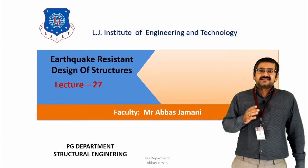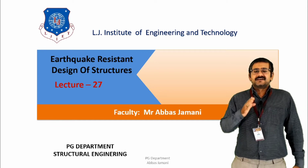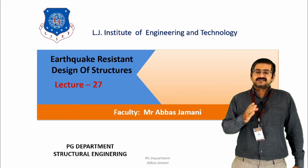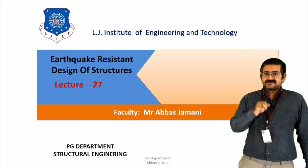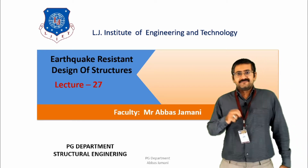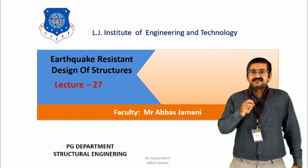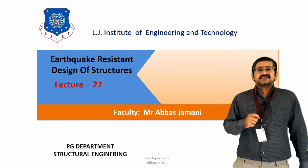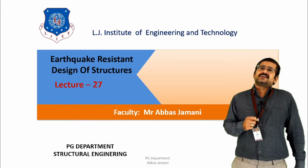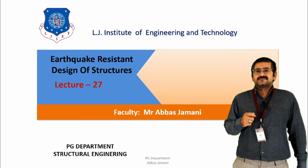So basically the fundamental of the Indian code is that under no circumstances should the structure collapse. And we have also discussed two basic types of earthquake that the code talks about, that is, the maximum considered earthquake and the design earthquake, right? And we have seen that if you go for the maximum considered earthquake, then the structures are going to be uneconomical in nature, as the probability of these earthquakes is very low.